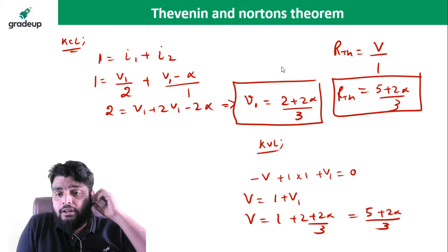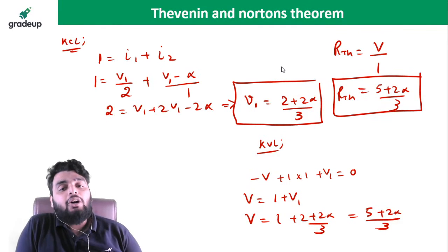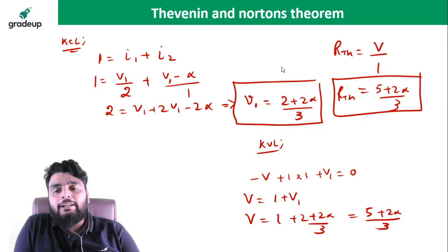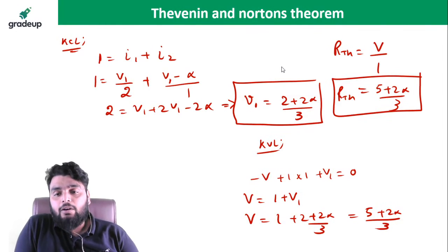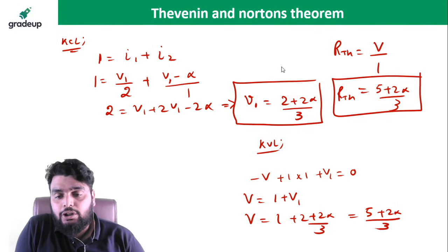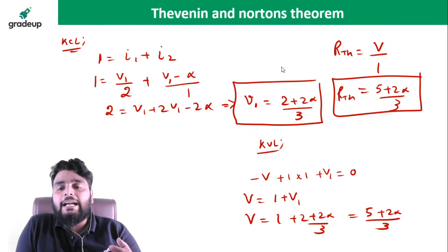Now ask me your doubts. Rishabh Pandey and Chinni, your answer is wrong, beta, because where is the alpha? Where did you forget alpha? That's why the alpha must come with the RTH. Now Sheikh, in the given question, the VTH is 0. Yes, beta. In this question, VTH is 0 because this is a dead network.